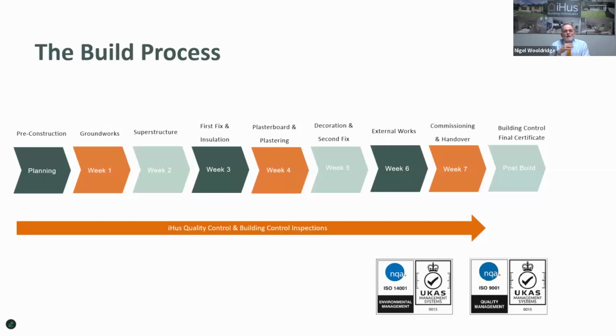Our foundations, we have three styles of foundation. We have a hexagonal screw pile, which are literally artesian screws up to 3 meters in length that are driven into the ground. So they sit on a plinth for the annex to sit on. Second one is a standard concrete pile with a thing called a swift plinth, which is like a little pyramid with an adjustable thing for making the levels perfect. And worst case scenario would be a concrete pad.